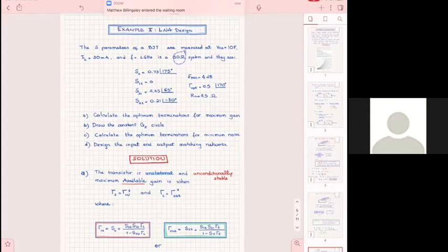You get scattering parameters at one frequency. And then you plot them over, I don't know how many frequencies. Well, it's not correct. You remember how when you get pages and pages of specs for a transistor, you see that every frequency you have different scattering parameters.